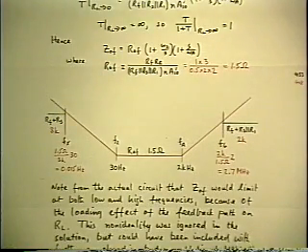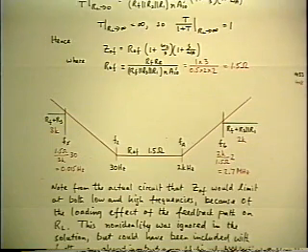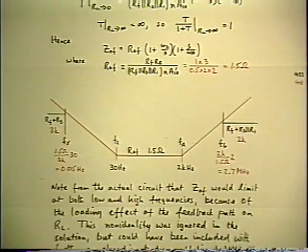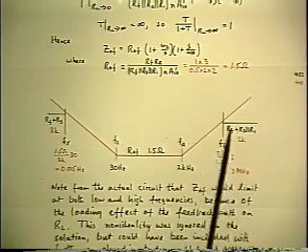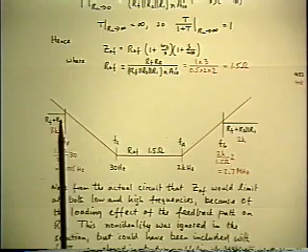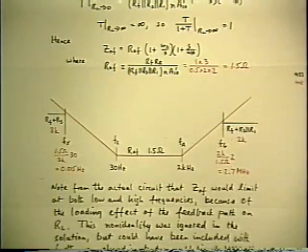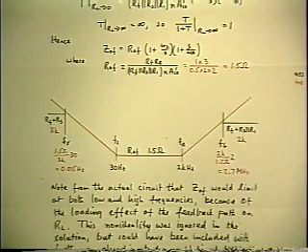So we've fixed up the answer anyway, and the bottom line conclusion is we don't care anyway. We don't care what happens at 15 millihertz or 2.7 megahertz, because we know very well that the basic model we started with has fallen apart long before you get to those frequencies anyway.